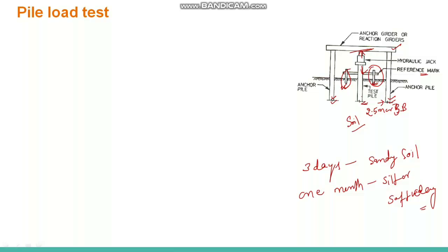So after completing this setup, we have to leave it for 3 days in case of sandy soil, and for 1 month in case of silt or soft clay.